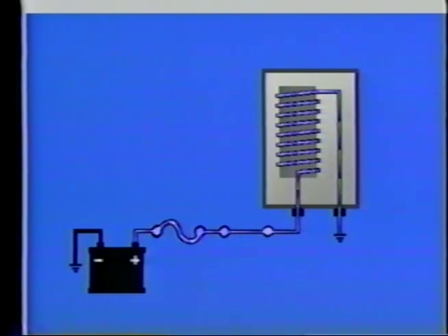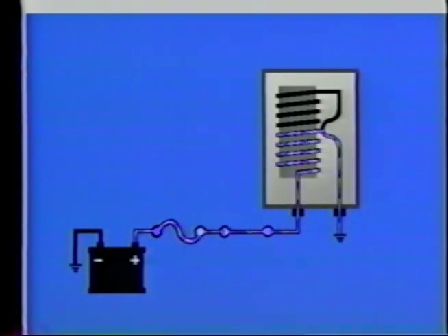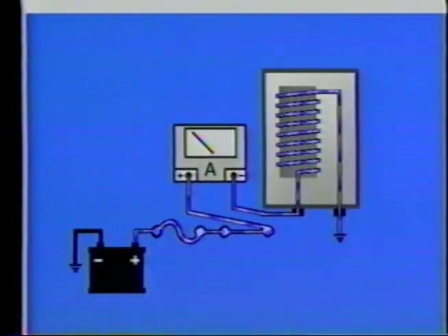Another short to power involves improper contact of a conductor within a given circuit. A common example would be wire-wound armatures, coils, or solenoids, where the contact point eliminates portions of the coil, reducing designed circuit resistance. In this case, an ohm meter does a good job of locating lower than specified resistance. Alternately, if correct circuit amperage is known, inserting an ammeter in the circuit will also identify shorted resistance coils in operation. You'll see higher than expected amperage in the circuit because of reduced circuit resistance.